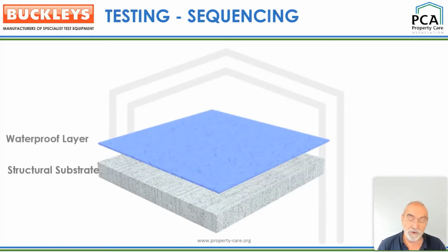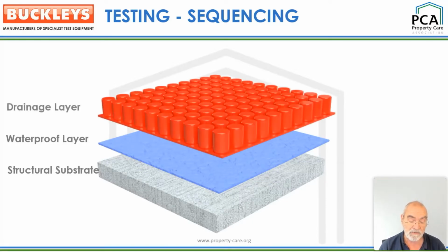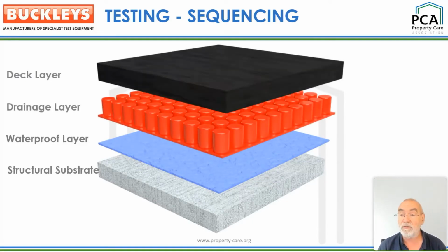The sequencing is important. Regardless of the approach used, inspection for and detection of leaks on a rooftop substrate before occupation is crucial for the architect, building and roofing material suppliers, and contractors and clients themselves to ensure the building meets and will continue to meet design and specification. Even if a permanent monitoring system is specified, it makes sense to inspect thoroughly before any overburden is added. If the waterproof layer will be covered by a traffic deck or vegetation layer, and particularly so if a permanently installed system is not used, it's vital to ensure waterproof integrity.